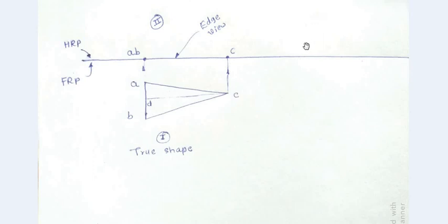We had kept the element which we have kept free on the left hand side in the HRP, and we had given inclination to this edge view as per the specification, and we had completed this third step of the changed front view of the edge view, and from this changed front view we had drawn the changed top view. This was our usual sequence of steps for all the earlier problems.